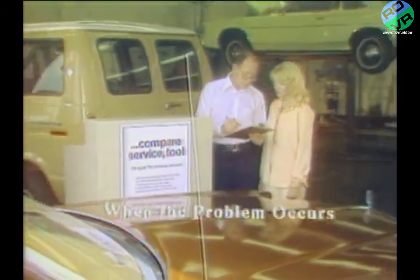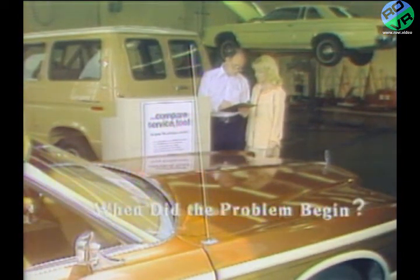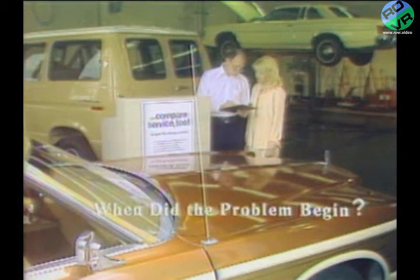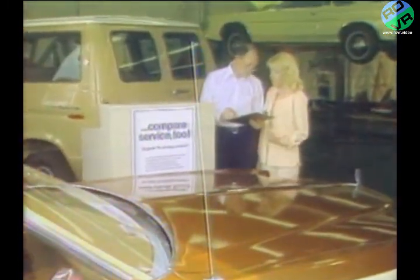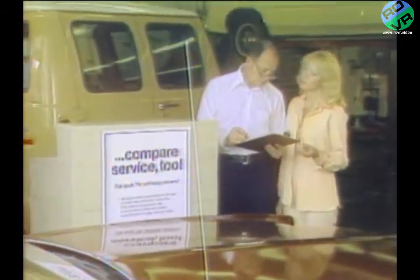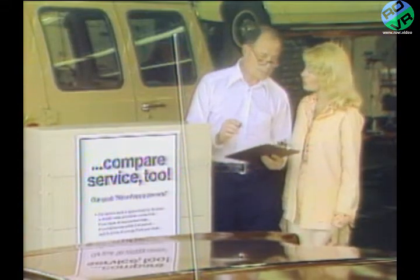Find out when the problem occurs, at what speed, in which gear. Did the problem originate when the car was new, or did it happen recently? Get as much owner information as possible, because talking to the owner is one of the best ways to help you diagnose and isolate an NVH problem.